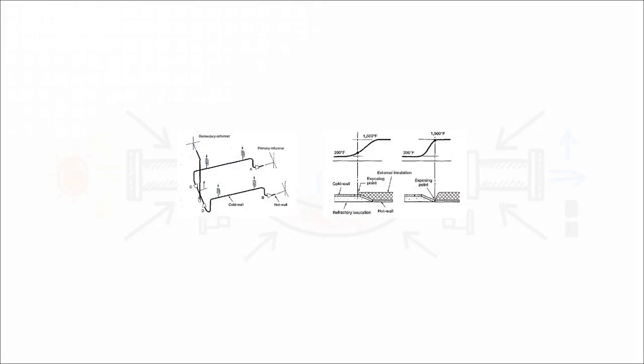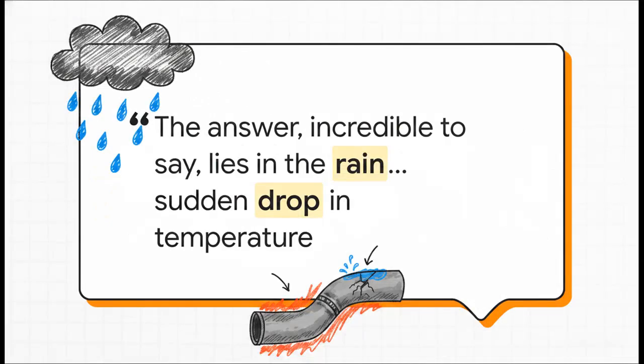The solution was finally uncovered by a sharp-eyed engineer who just started comparing before and after maintenance photos. During that routine maintenance 10 years in, the contractors had missed a tiny, seemingly insignificant strip of external insulation right over a critical weld. In the original design, the exposed weld hovered safely at about 500 degrees. But because of this one tiny missing chamfer of insulation, that exposed joint was now rocketing to a blistering 1500 degrees Fahrenheit.